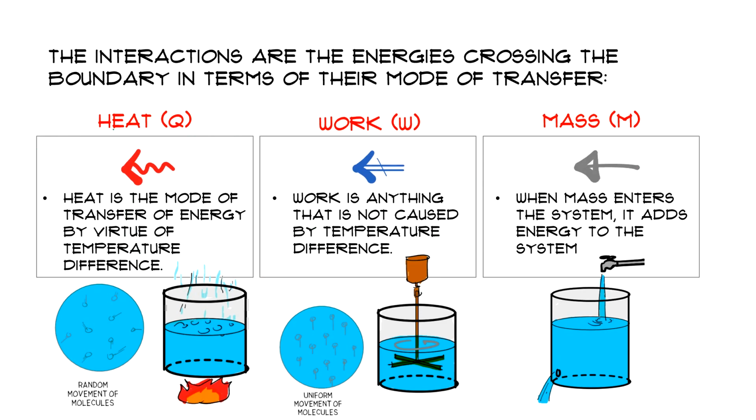It refers to the mode of transfer of energy. So take note, it's not the energy itself, rather it's the mode of energy transfer. So in terms of modes, we can transfer energy into or out from the system by heat, or by work, or by mass. So in terms of heat, it's a mode of transfer of energy by virtue of temperature difference.